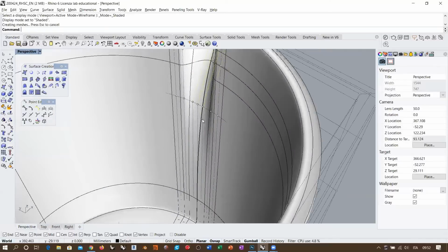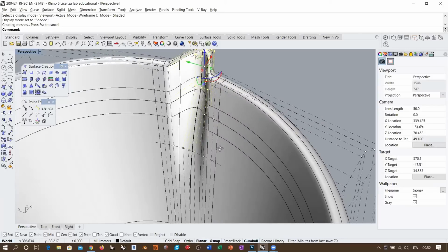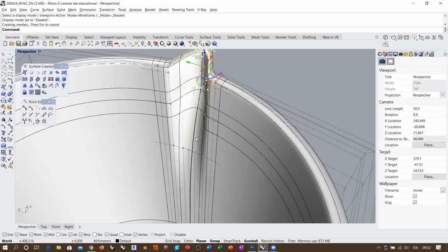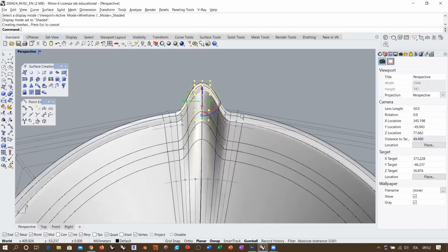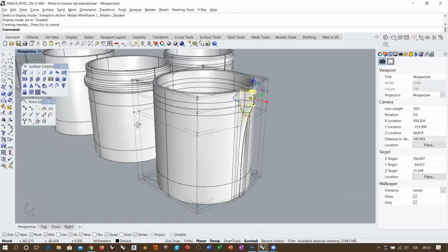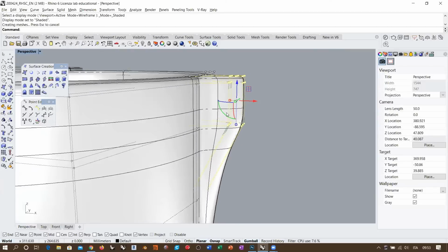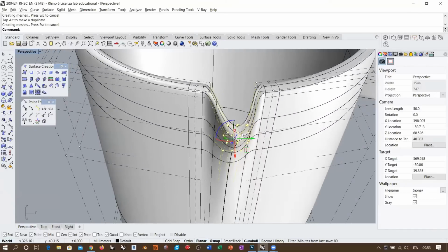So you see that the internal edge is deforming smoothly because I'm not working on kink points, or well, yes, I'm working on kink points, but on the profile direction, okay, which is smooth. And it's not producing any kink in the horizontal direction because I have created this structure of control points here on the sides, okay? And I'm not touching this face of the original cube, let's call it so, and this face of the original cube. So everything stays smooth in this case. And I can play with these points as I want, like also creating this, because I'm not changing anything that regards the kink aspect of this surface.